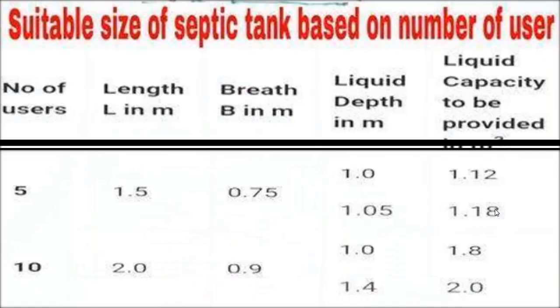And then here are the suitable sizes of septic tank based on the number of users. Here: length of septic tank in meters, breadth of septic tank in meters, liquid depth in meters. So minimum depth and maximum depth I have given here. Then the liquid capacity to be provided in cubic meters for different numbers of users.